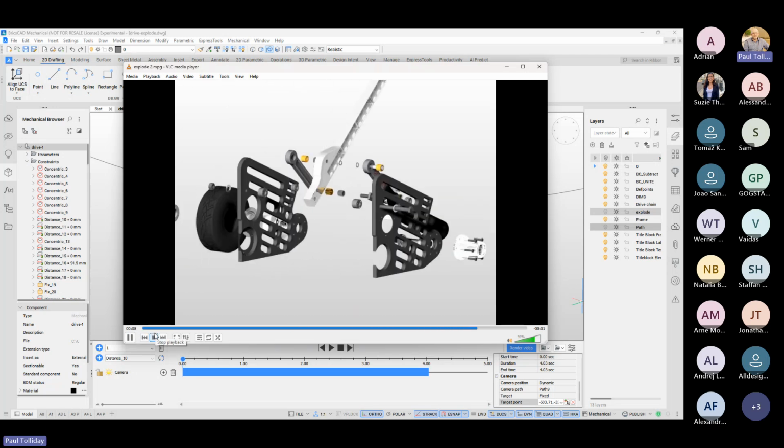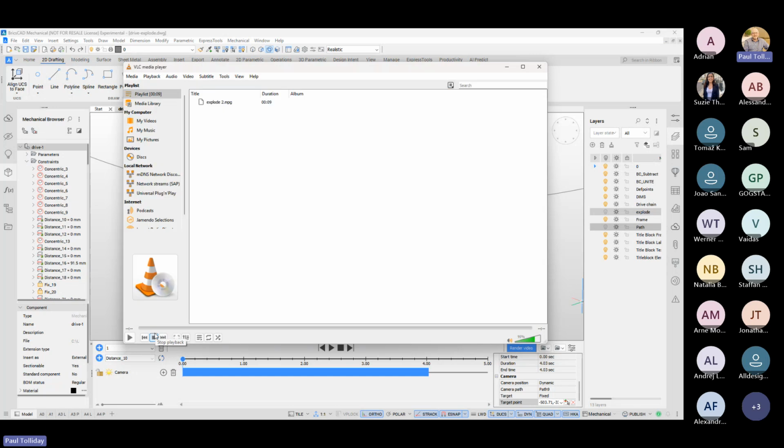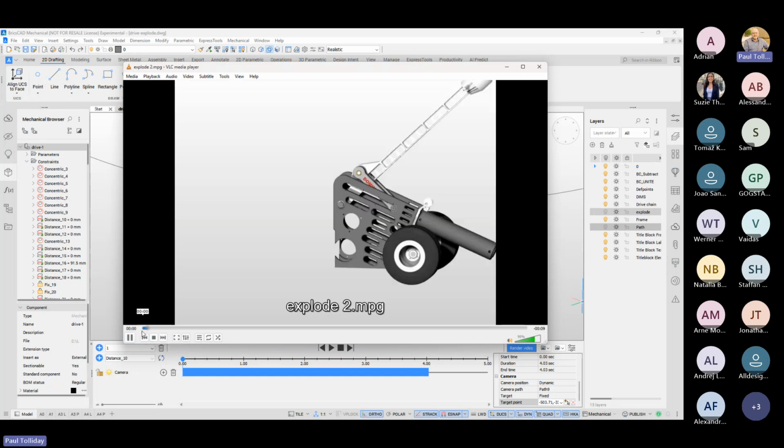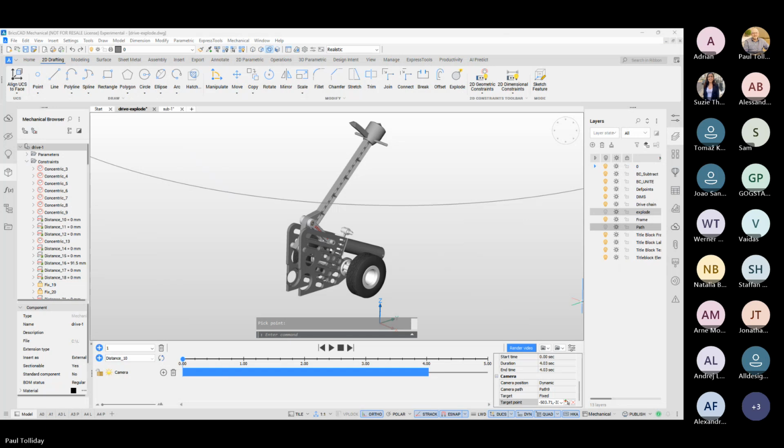Now, you can see that this view is now being exploded. And at the moment, all we've done is work with parameters as they come through from the model. Now, I'm going to get onto the exploded view a little bit later, but there's a few things to be aware of. When we're working with this model I've got at the moment, you'll see everything is at top level. So there's no sub-assemblies and there's no blocks. They're all single parts and constrained by the 3D parametric constraints in this assembly. If you're working with a large assembly, you're going to have blocks and sub-assemblies in there.